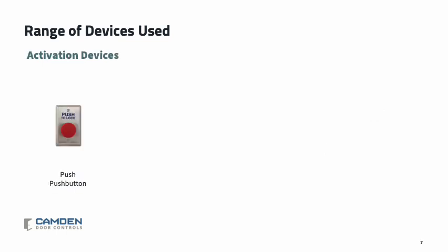One of the most important choices that system designers have to make is in the selection of the activation devices that are used in the system. Push buttons are available in a range of configurations, including mushroom buttons, like the model that's shown here, but also includes other types of push exit buttons. No-touch switches have become extremely popular as a response to COVID-19 and make a lot of sense in restroom applications. If you select this option, there are some important design considerations, and we'll talk about those in a few minutes. It's not simply a matter of replacing a mechanical switch with just any touchless switch.